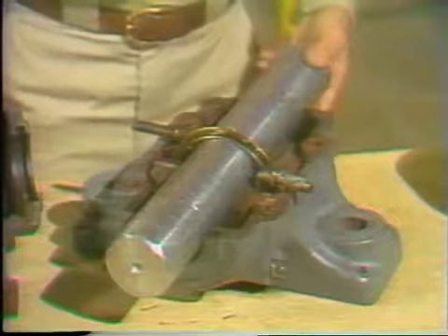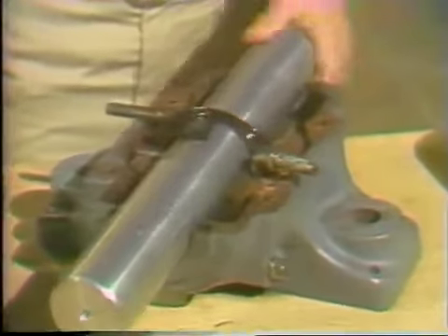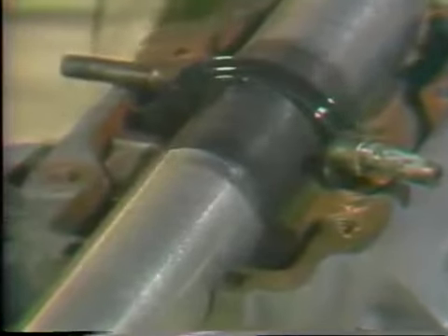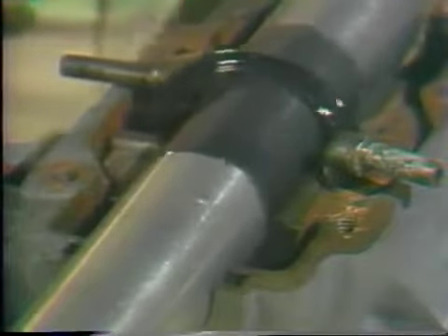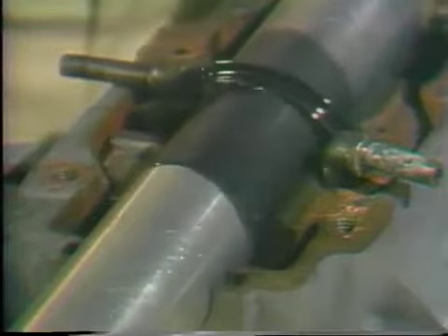So, when the ring and shaft turn, oil sticks to the ring and is deposited onto the shaft during rotation. The oil then spreads throughout the bearing and proper lubrication is achieved, as you can see here. A continuous film of oil is supplied to the bearing and shaft by this method.